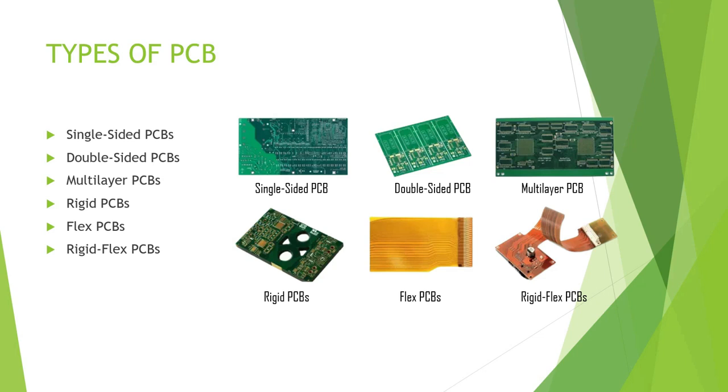The most important advantage of the two-layer, double-layer PCB is that it reduces the size of your PCB, making it more compact. A single-sided PCB takes much larger space, because there is only one side for components. With both sides in use, we can reduce the board size by assembling components on the two layers, the top and bottom of the board.